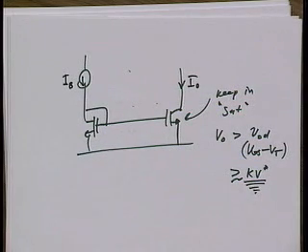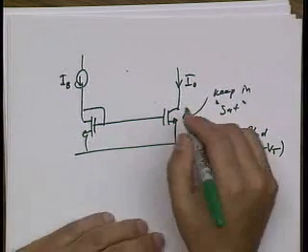Anybody? If these were bipolar transistors, what would the systematic error be? That's right, base current. It would be due to base current. Well, how about for MOSFETs? That's right. You want to use a mic? Difference of the VDS of the two transistors. Very right. That's exactly right.